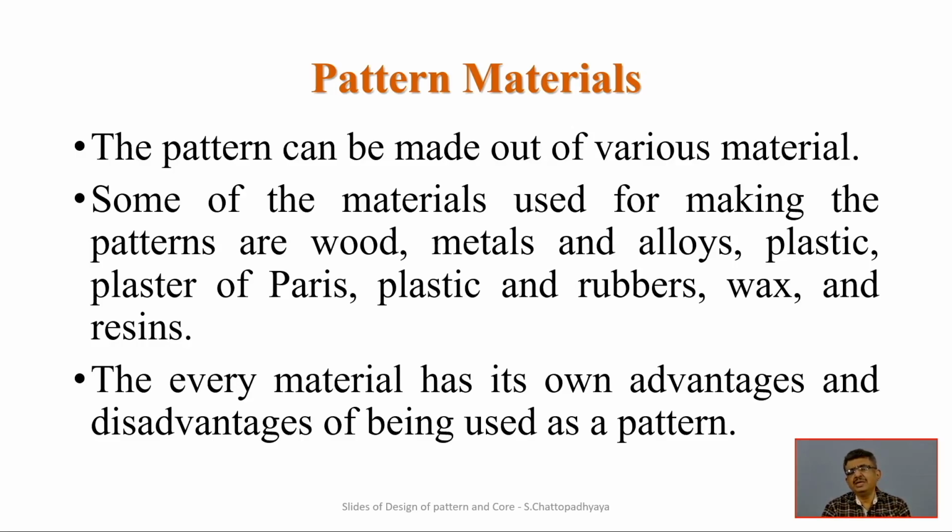The problem with wood is its dimensional changes in different seasons if it is not seasoned wood, and wear and tear and jeopardy of those surfaces are issues in wood. Wooden patterns have less lasting life. Some alloys are also used to get the advantage of different combinations of metals. People are using plastics also, because plastic is very easy to manufacture at lower cost. People are using plaster of Paris also, easy to give shapes. Then plastics and rubbers and wax and resins. Many things can be used.